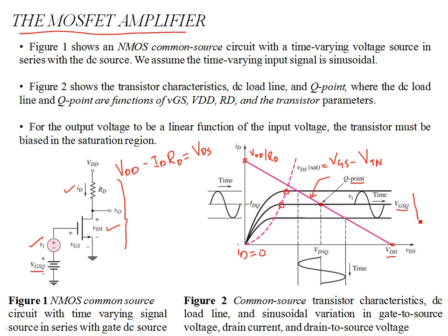As you go on increasing VGS, the drain current is increasing. That can be explained from the physics or the construction of the device. But from this equation, you see that the VDS sat, which is given by these circles, the intersection of this dotted line and these solid black lines, are the transition points from non-sat. This is your non-sat or ohmic region, and then you have your saturation region over here, which does not depend on VDS. As you go on increasing VDS beyond saturation, the ID is pretty much constant. It does not depend on